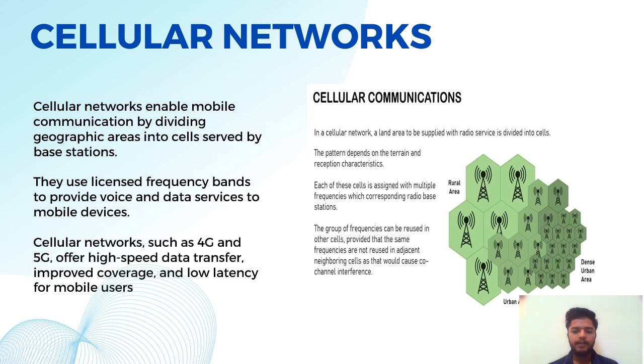each of the cells is assigned multiple frequencies with corresponding radio base stations. The group of frequencies can be reused in other cells, provided that the same frequencies are not reused in adjacent neighboring cells, as that would cause co-channel interference.